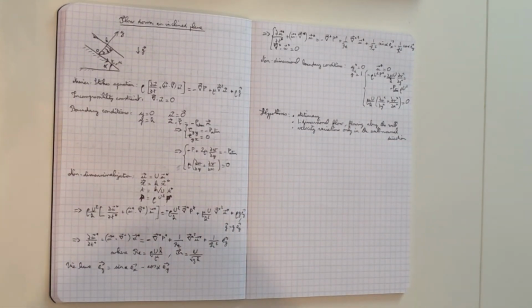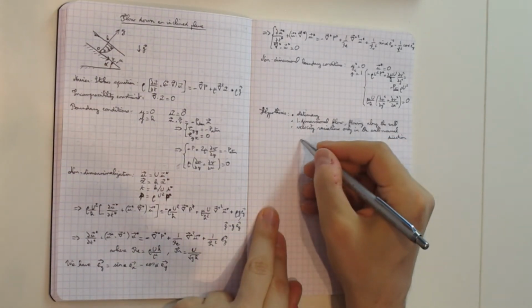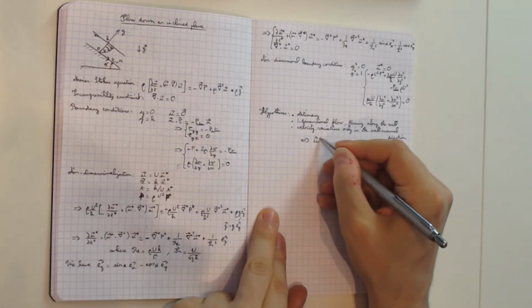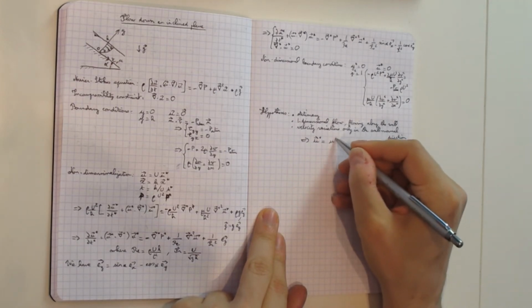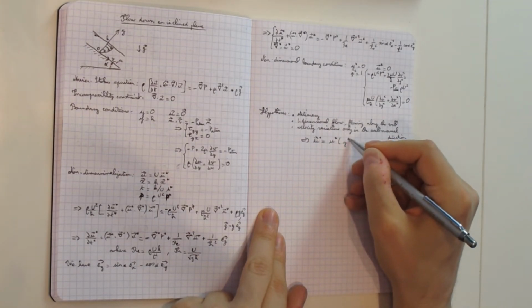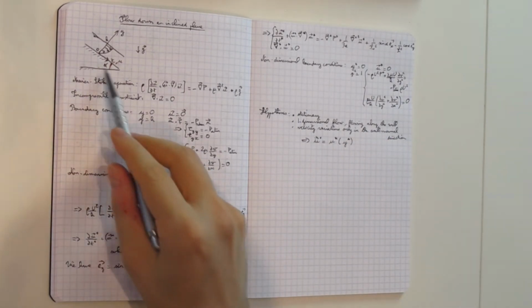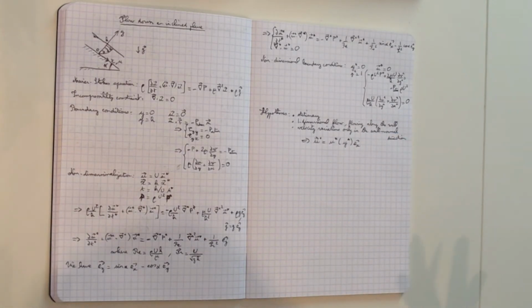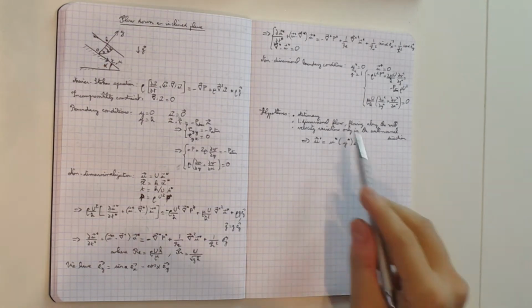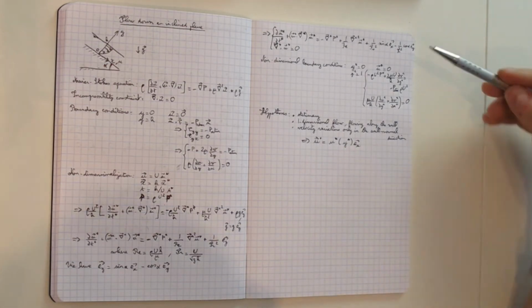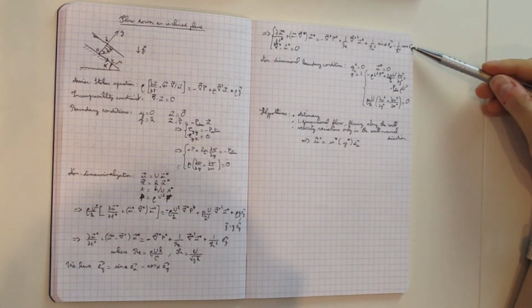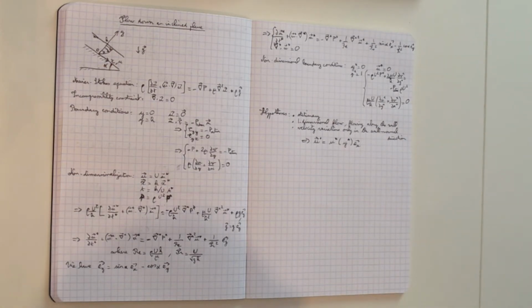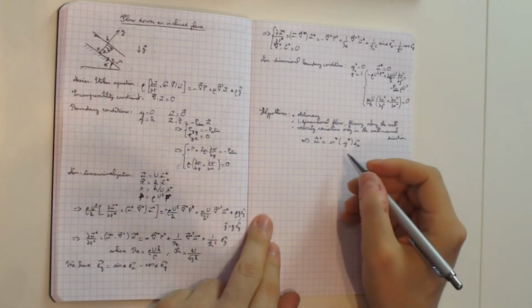And these hypotheses lead us to write that the flow can be simplified into u star as a function of y and not of x and not of time in the x direction, and no other component in the other direction. So that is going to dramatically simplify our equations. So based on these hypotheses and this writing for the flow, we can write down the Navier-Stokes equation in its component form in these two-dimensional problems.